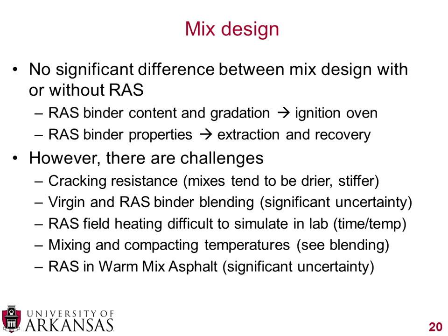There's a lot of questions surrounding how much blending there is between the virgin asphalt cement you're using and the RAS binder that's being added to it. And this is also a topic I think that's pretty open with recycled asphalt pavement, RAP. So with both RAP and RAS, I'm not sure if we fully have our heads wrapped around how much they actually blend together.